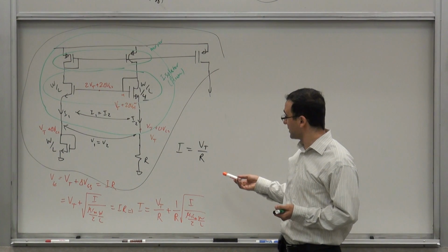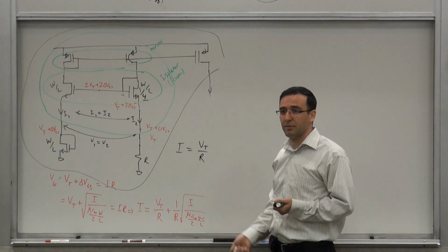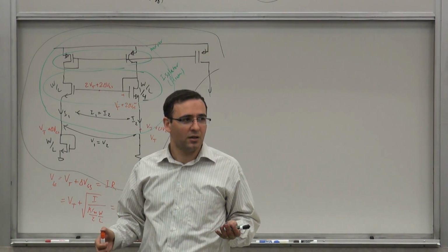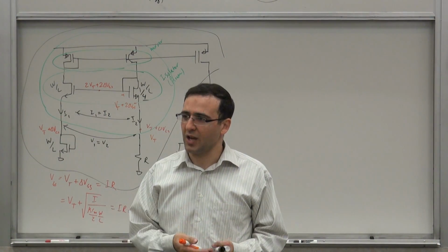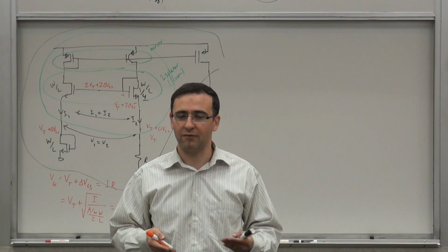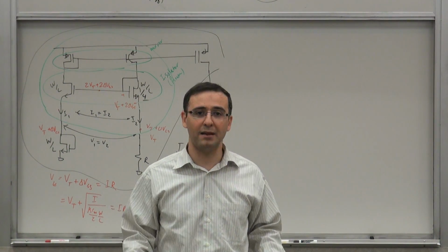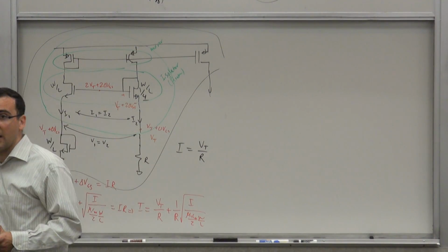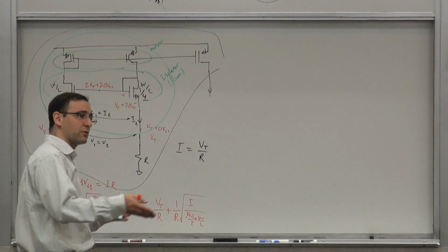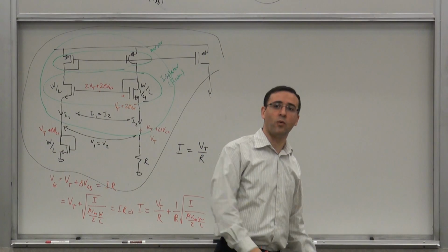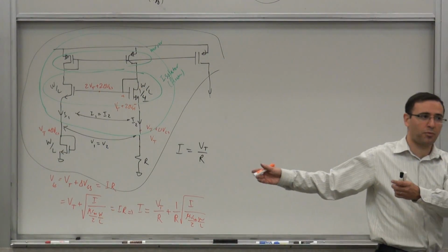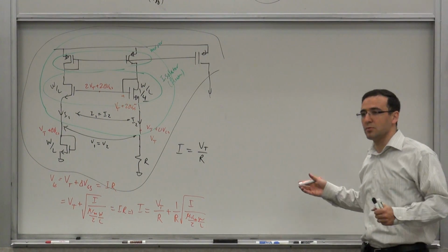Well, we clearly have process dependence because both VT and R depend on process. What determines the threshold voltage? The implant charge in the channel, and that can vary from one transistor to the next on the same wafer or die. It can vary more from one wafer to another, and even more from one lot to another. One time you make one set of chips, and the next time, like 3 weeks later, you make another set of chips, and they will be more different.